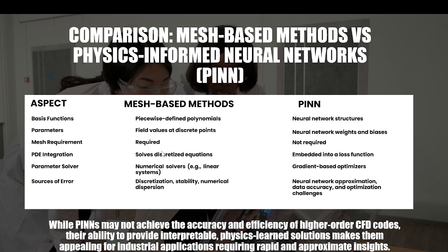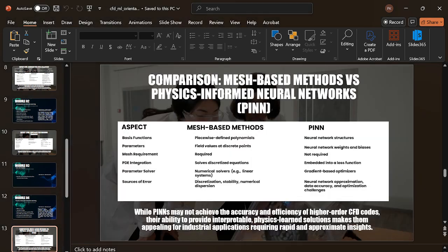But some things that you are going to understand here, because if you speak about the mesh requirements, if you are using CFD, the mesh requirement is a very important thing. With a complex geometry, very complex mesh generation is required, because if your mesh is not good, then you will lose accuracy, or sometimes you are not able to get the proper solution.